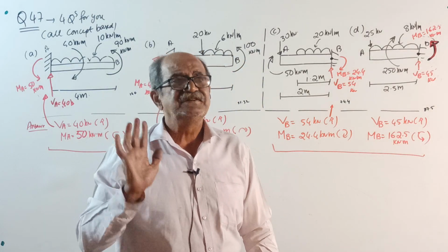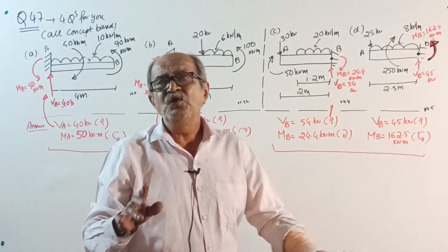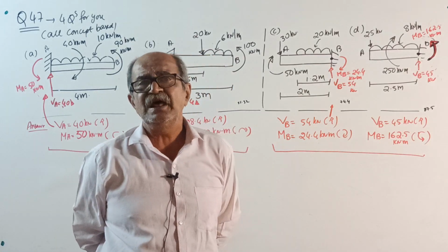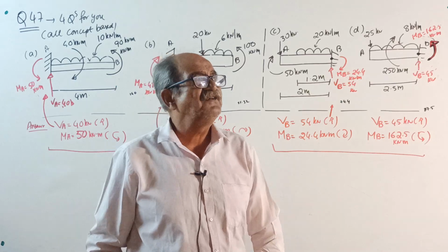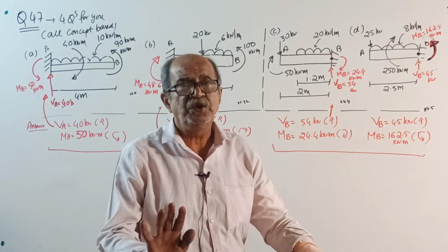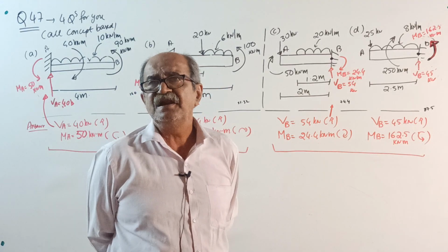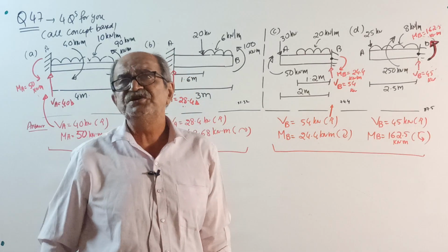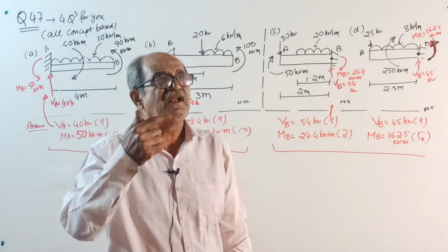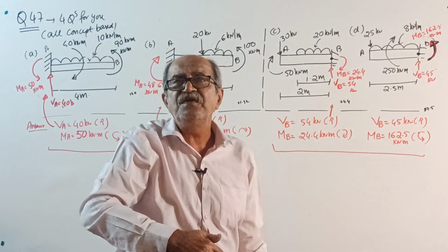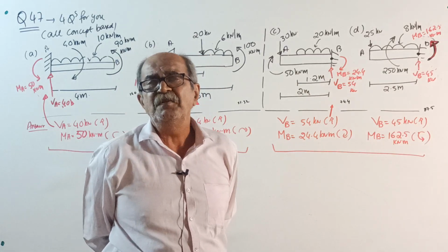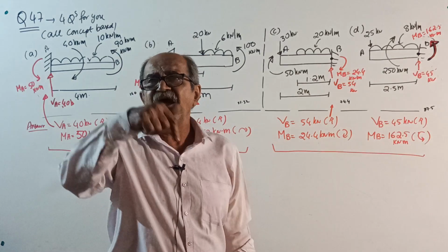Those who want direct answer, what you do is, see, all of you assume vertical reaction upward for usual loading, for those who are going for systematic calculation. But if you want a basic concept and solve the question by using principle and fast get the answer, then what you do I will tell. First, vertical reaction at the fixed end. There is only one support, there is no sharing of load. Whatever loading on the beam is action, opposite is reaction. Whatever net downward load is acting, opposite upward is the reaction. So vertical reaction, no problem. Rare case, if the load is net is upward, reaction is downward.